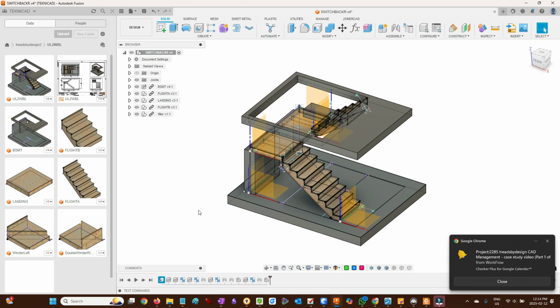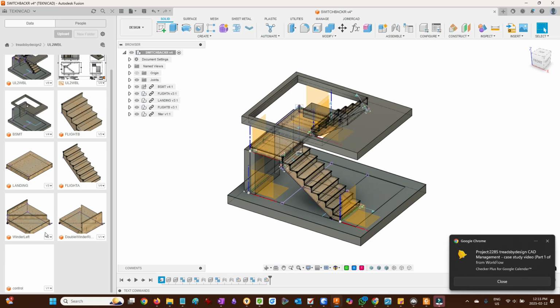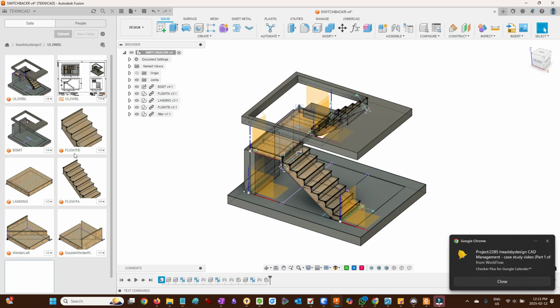Here's another take. A company contacted me concerning creating a custom library for their construction grade stairs. They wanted to shorten the creation of shop drawings for an entire house from over an hour to 15 minutes. And so this is the system that I came up with. It uses a derived file. It uses distributed design, which means that the components are linked. And of course, it's parametric.